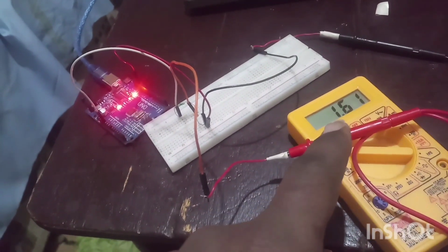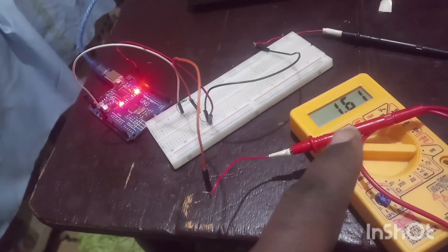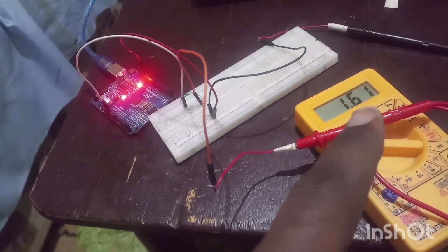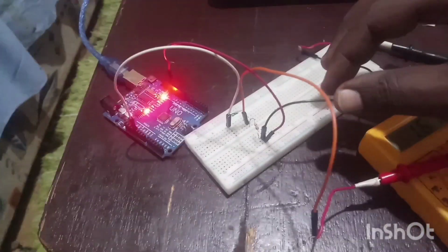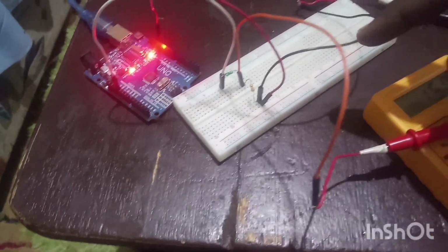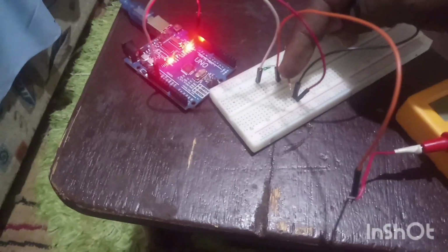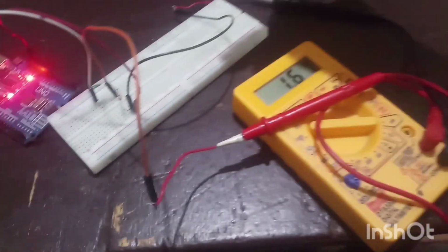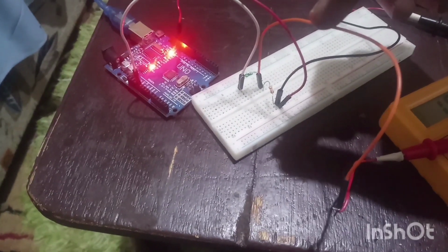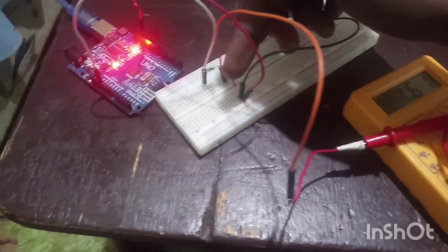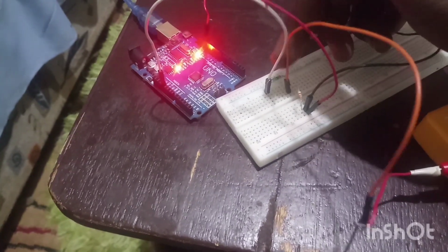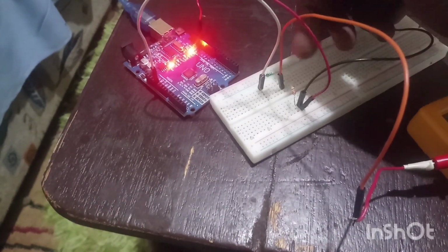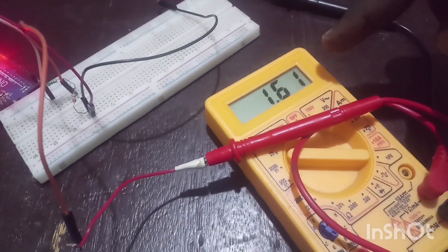There it's showing you 1.60 volts. These things are quite delicate, so I don't know how I can deal with it. You see, this is a jumper wire which is connected to the top of this resistor where my hand is pointing, and I have another jumper wire here which is connected to the bottom of this R2 resistor. This is R2 and that one is R1. So I'm measuring just this R2 and it's showing me 1.61 volts.